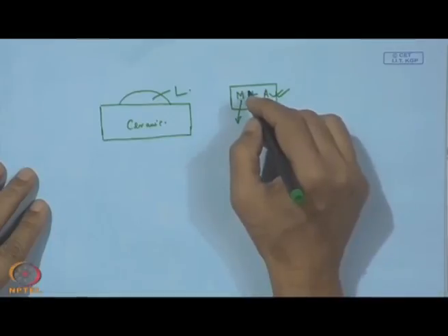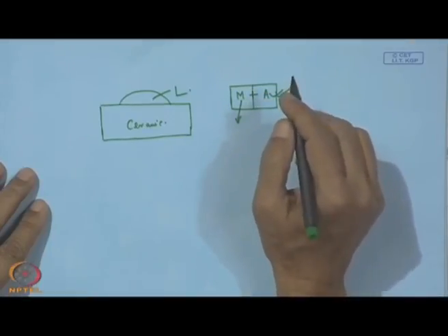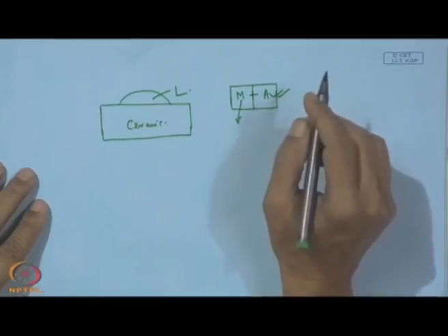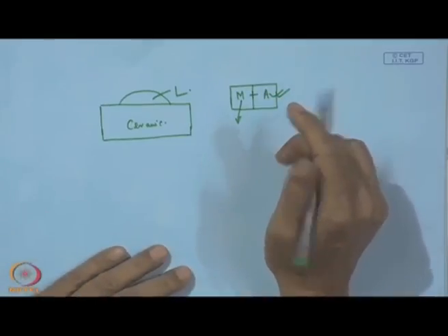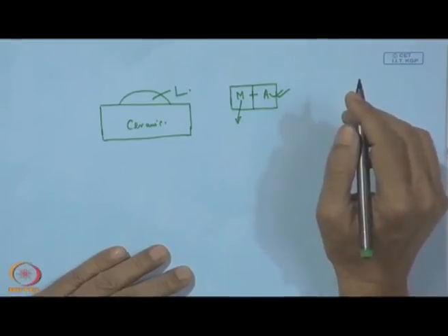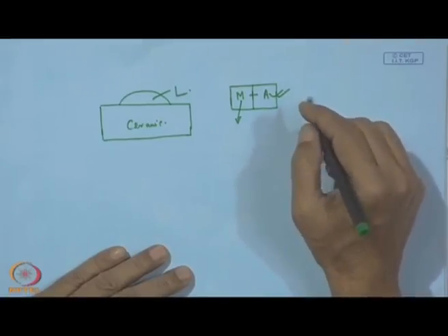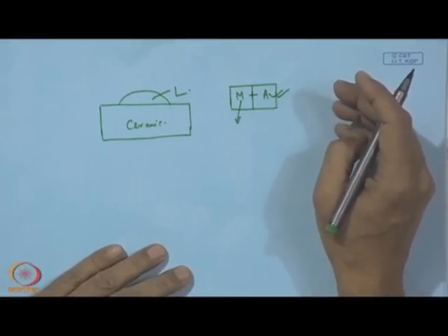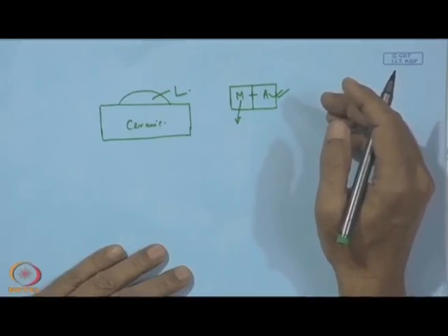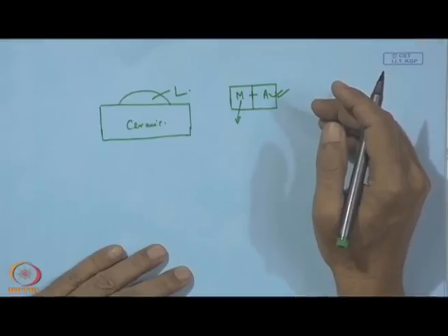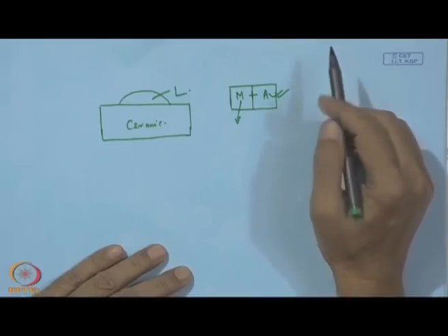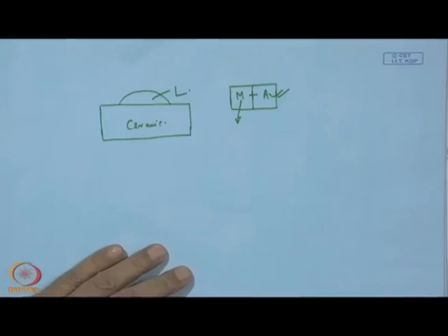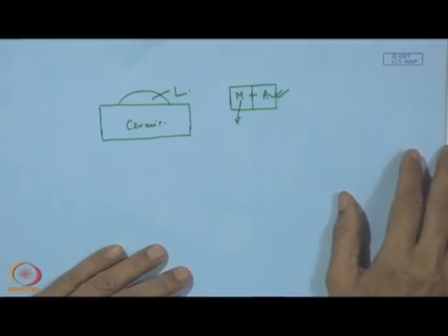By this activation of the conventional metal through the addition of a strategic material, and these strategic materials are mostly found among the transition elements, which are known as carbide formers, oxide formers, boride formers, or even nitride formers. So, these materials are strategically chosen and added to the parent material to make this surface quite active, and that can increase the wettability.